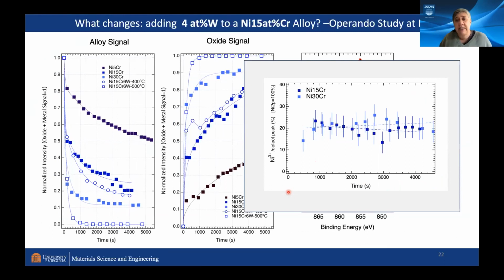So these are defect states which are present in the oxide: vacancies, chromium doping of the oxide, some tungsten maybe in the oxide. This is very characteristic for oxides which are grown on binary alloy systems. These are vacancies or interstitials which are needed to continue the oxide growth, because you need transport through the oxide. So these defects are built in very, very early in the process.